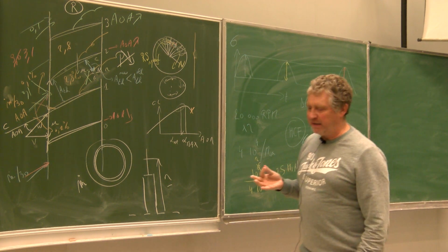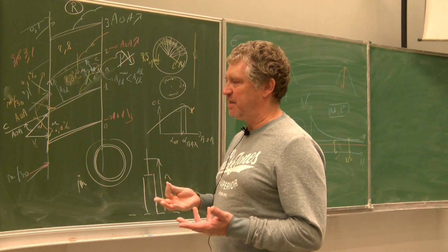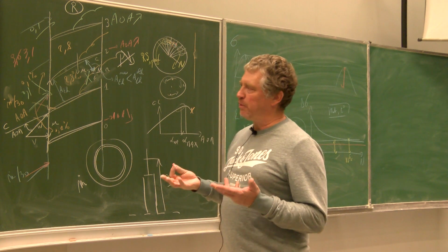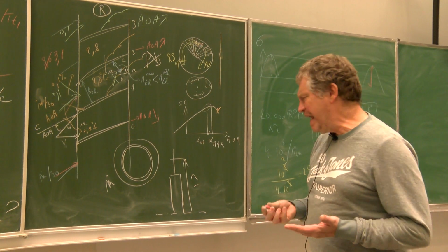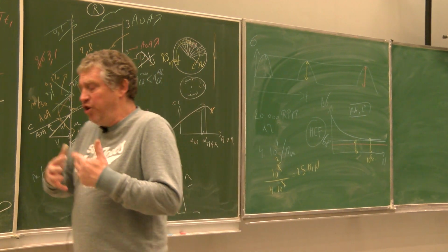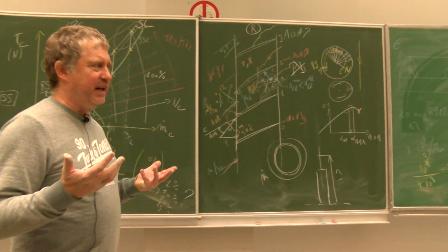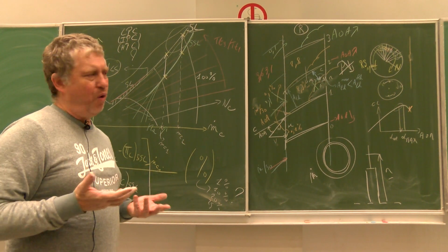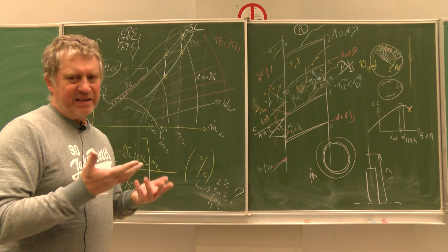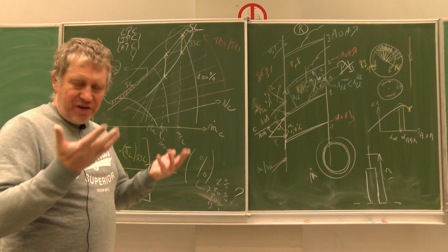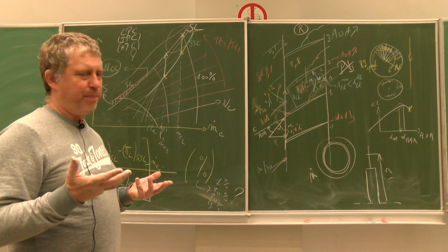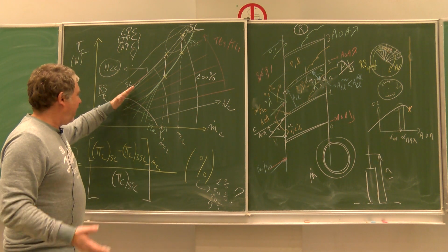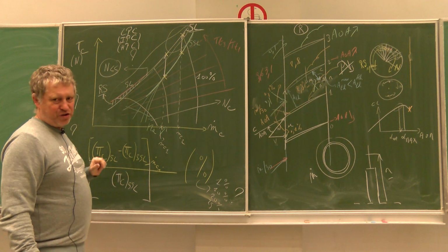that you solve by different design circumstances, selecting a better material, reinforcing the material by laser shot peening or things like that. And globally speaking, normally if you take the right materials, reinforce the materials, and do the right analysis to be able to work with these rotating stall cells, 1, 2, 3, 4 in the compressor, this is totally allowed. And that's why you will extend the zone.